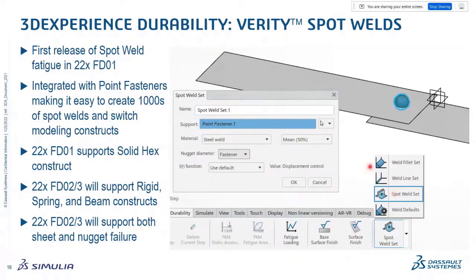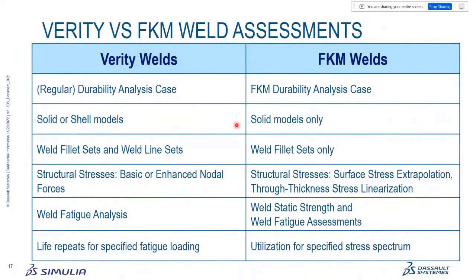The spot weld, of course, has a very simple interface. Okay. And you can choose which fastener to pick from the spec tree, right? Just a little comparison between Verity and FKM welds. So you can do Verity welds along with regular base metal fatigue in a regular durability analysis case. FKM, you need an FKM durability case.